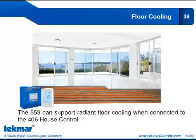Now the nice thing about the 553 is if it is controlling cooling equipment and the floor cool setting is on, it can provide a switchover call to the 406. So it has that capacity to provide the switchover call to the 406, whereas the 552, since it's not controlling cooling equipment, cannot provide that switchover call to the 406.